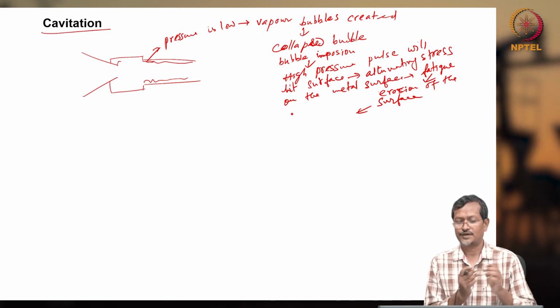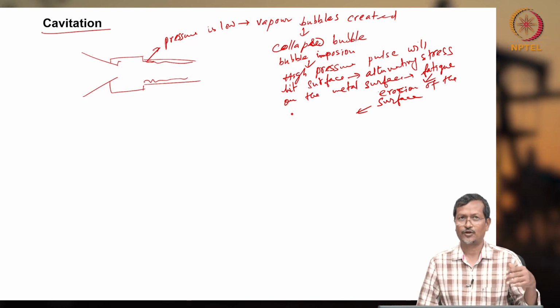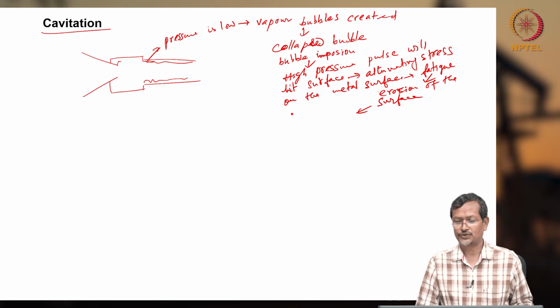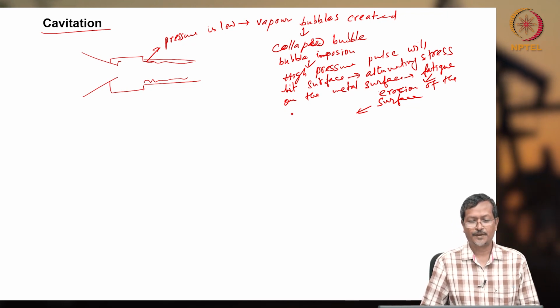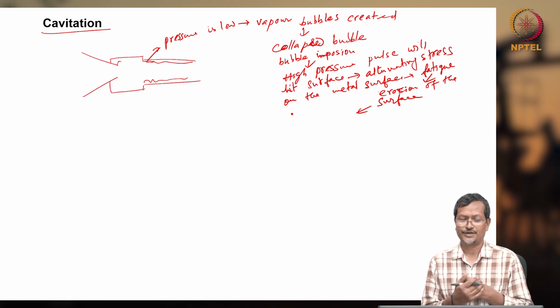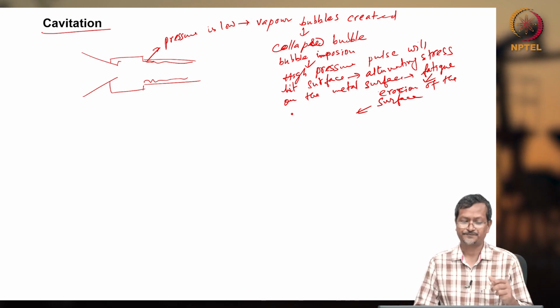If you are not considering it, then because of this erosion, after some time, like I already told, this jet pump's normal life of 4 to 5 years will be lower with erosion and cavitation. And the jet pump does not have any moving part. So if you are a design engineer, every time you have to think about reducing the number of moving elements in the system.